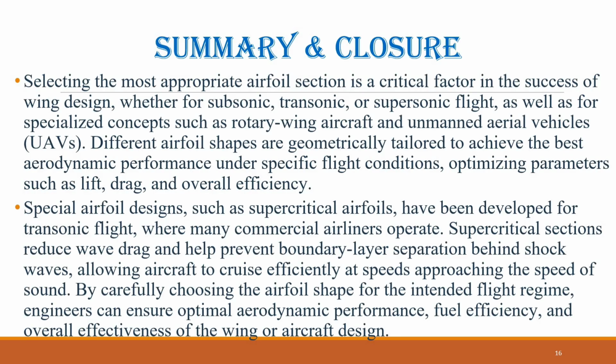Special airfoil designs, such as supercritical airfoils, have been developed for transonic flight where many commercial airliners operate. Supercritical sections reduce wave drag and help prevent boundary layer separation behind shock waves, allowing aircraft to cruise efficiently at speeds approaching the speed of sound. By carefully choosing the airfoil shape for the intended flight regime, engineers can ensure optimal aerodynamic performance, fuel efficiency, and overall effectiveness of the wing or aircraft design.